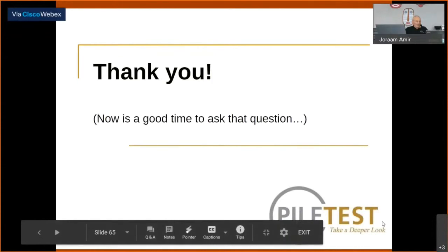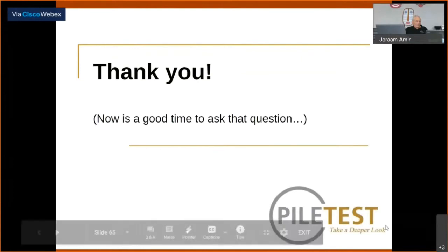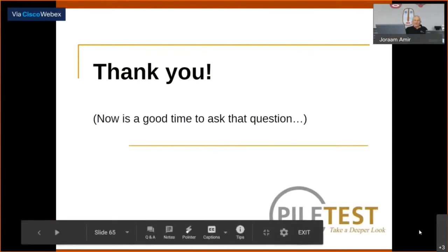Any recommendation for the installation number of access tubes? Well, in short, the more the better, of course. The more tubes, the more money it costs, of course. On the other hand, the more tubes you have, the better your resolution. So the best is to follow the rules of the ASTM: 1 tube per 30 centimeters of diameter.